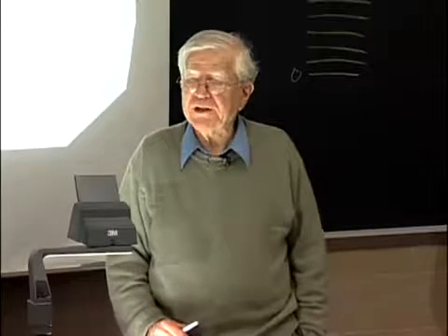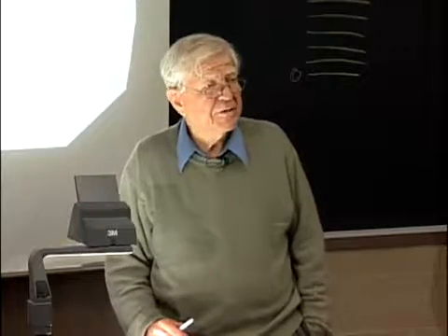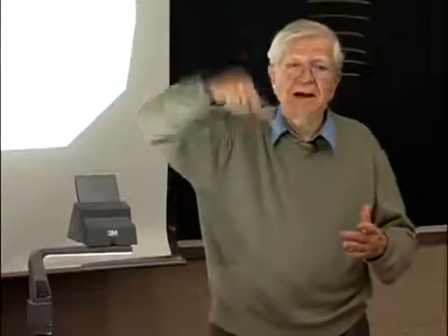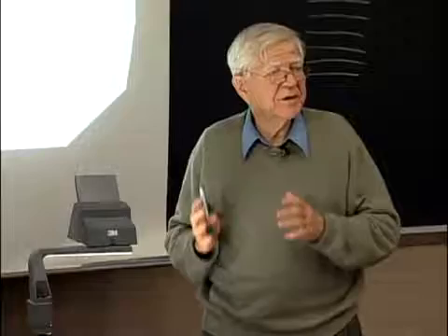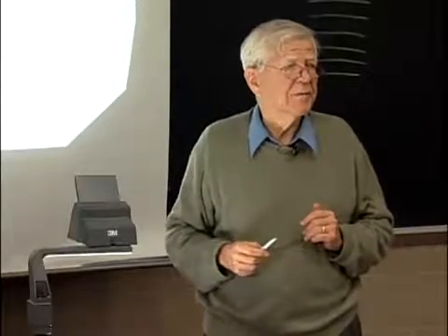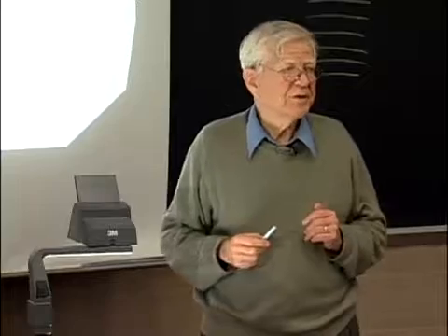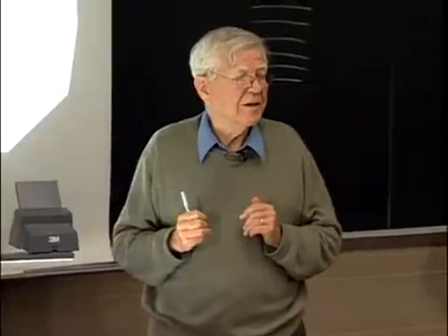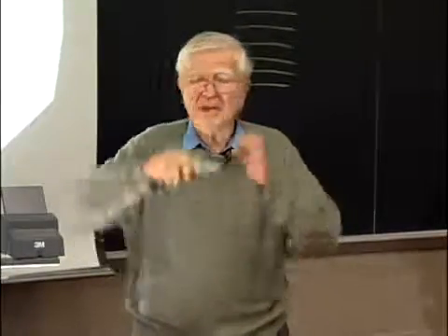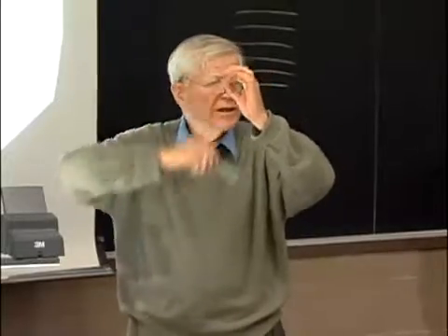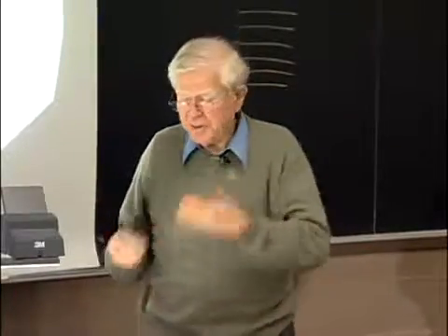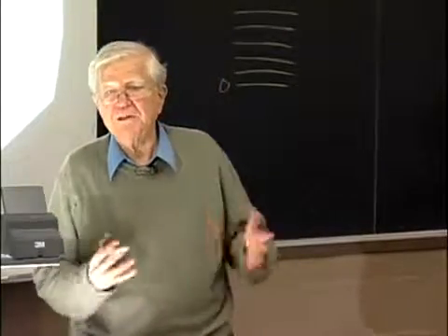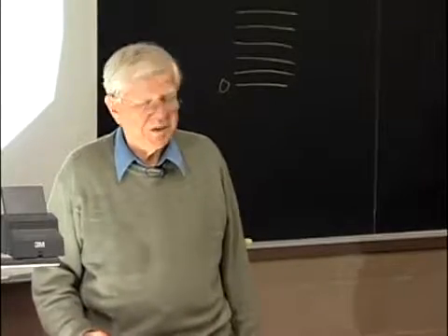How do you recover from frequency errors? Well, if I can recover from phase errors, I'm recovering from frequency errors also, because I have this clock which is running around, and I'm slaving the clock at the receiver to the clock at the transmitter. So long as I have very little frequency error to start with, simply by keeping this phase right, I can also keep the carrier frequency right, because the phase is just going around at the speed it's supposed to be going around. So this will also serve as a frequency lock as well as a phase lock. When you're trying to do both together, you build the phase lock loop a little differently, obviously.